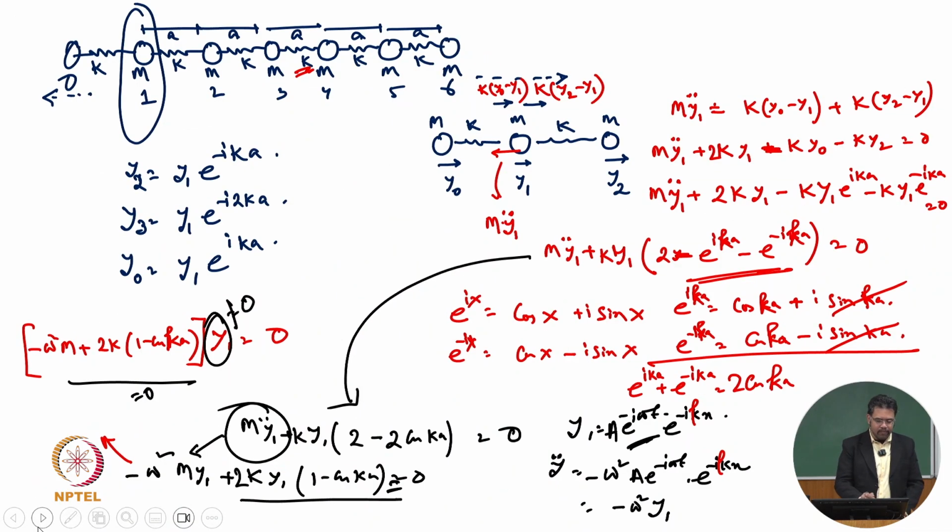Now if we implement the Bloch theorem into the equilibrium of the structure, we can solve and derive the dispersion relationship, which is the correlation between the wave number and the temporal frequency. And we saw a very interesting point: once we give a frequency to the structure, the wave number can be real, purely imaginary, or a complex number.